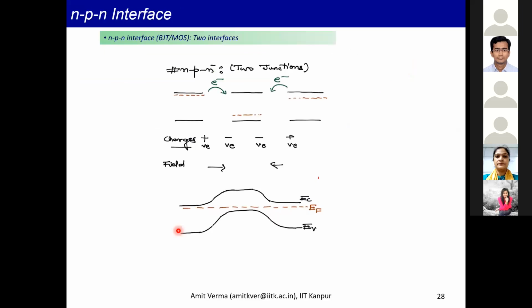Okay. So similarly, if we keep on looking at more band diagrams, suppose you're making an NPN structure, which can be either a BJT or say an NMOS. Essentially, you have these three parts in the device, you bring them together, you get a uniform Fermi level, and you will get a potential profile, or actually a conduction band profile, which looks something like this. Now, in a BJT or in a MOS, you have three terminals. Either emitter, base, collector, or you have a source, gate, and drain.